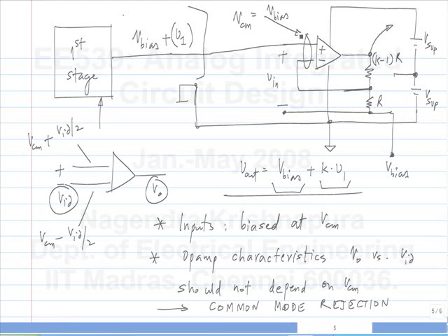So if you have a circuit which has a V bias value of 1.8 volts, but the maximum common mode voltage of your amplifier is 1.5 volts, then that means that you can't connect that amplifier to this amplifier directly. You may have to make some intermediate arrangement. So you have to change one of the two circuits, right? Okay, so that's the answer. If it so happens that the bias value that you are getting out from your other designs or somebody else's designs is incompatible with your op-amp, then you have to either change your op-amp design or place a level shifter between the two or something of the sort. Okay.